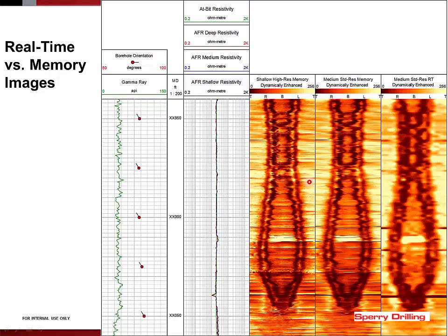This is the circumference of the borehole from left to right, which might be 18 inches or something in a 6-inch hole. So we're looking here at a bed which is an inch or two in thickness. In fact, there's 2 or 3 beds together which are all about the same thickness. So we're seeing a great deal of detail. In this case, we're traveling along a bedding plane and then just leaving it towards the bottom end.